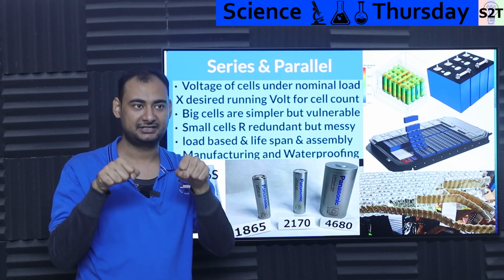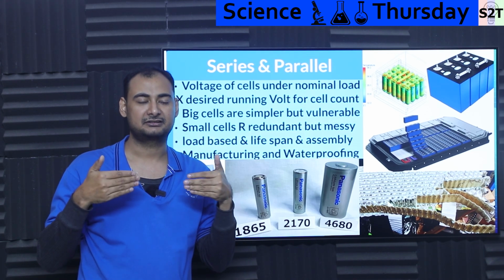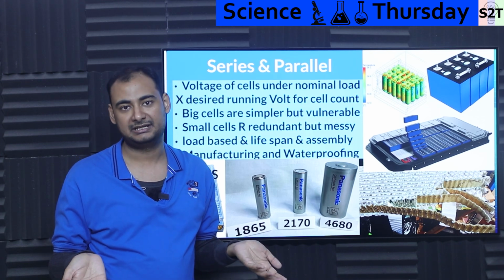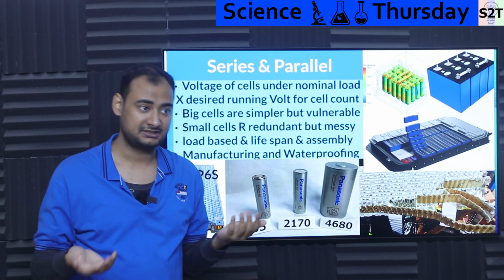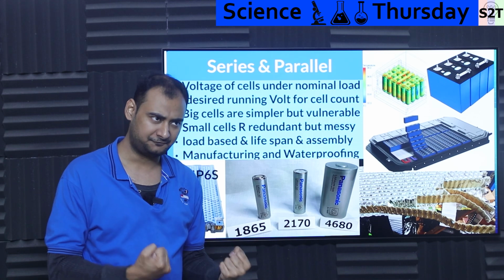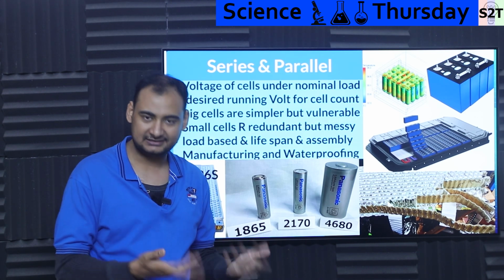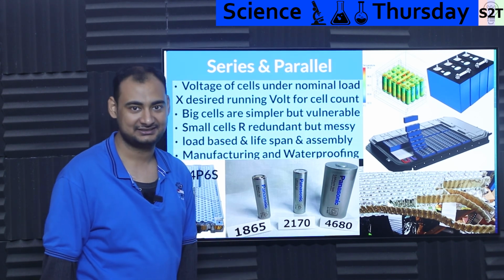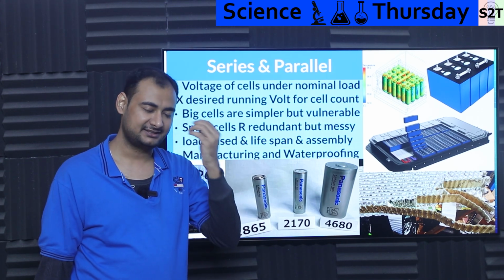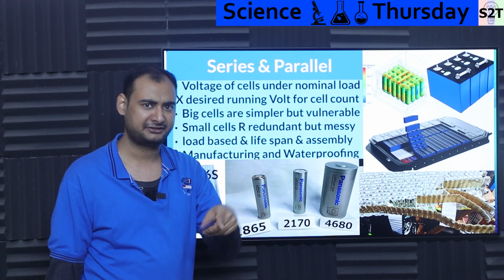There is a contactor there. But again, what happens inside the contactor, everything is still at main voltage. So if main voltage could be high, let's say 400 volt, 800 volt, 1500 volts, it is still there. So waterproofing is very critical. And I think this is the primary reason why electric cars catch on fire after being flooded.